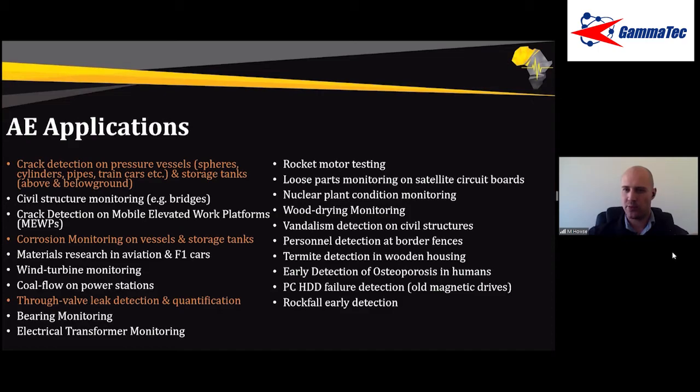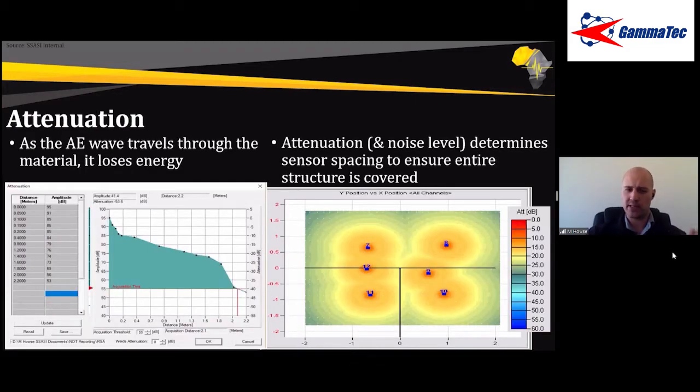Okay, what parameter has been used in terms of number of sensors? When determining the number of sensors, it is basically all up to the background noise level, which we can say, in this example here, is the acquisition threshold. So everything below 55 on this graph, we can say that's noise. There's pumps running, electrical noise, etc. And if we move this acquisition threshold up, because this is the curve, let me just start there first.